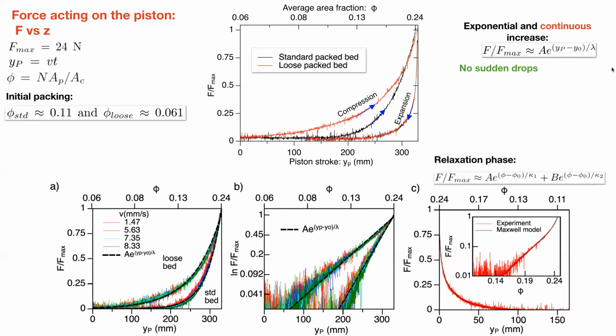Well, for the relaxation phase, I haven't discussed this during this talk, but in all cases, for all the materials, it's basically well described by a Maxwell model with two exponential terms, with two different time scales. This model is able to describe well the compression force versus the piston stroke.